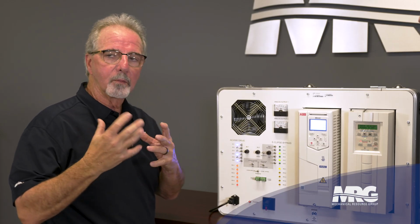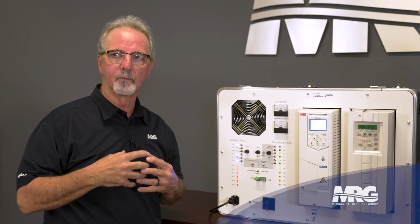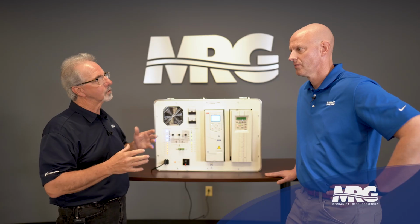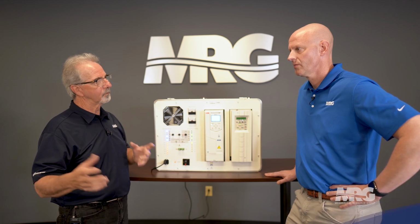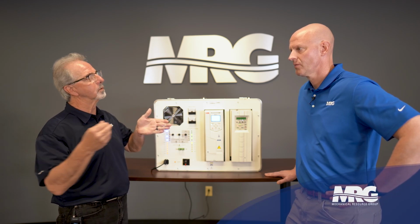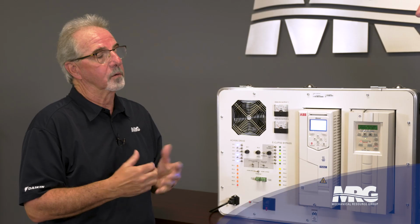Now remember, guys, we don't want smoke to invade the stairwells because that's your evacuation point. Those doors are going to be opening and closing quite a bit. If there's smoke on the floor and you open the door and there's not more pressure in the stairwell, smoke will come in, and then it's just like being on the floor. Yeah, it turns into a chimney. Yeah, it turns into a big chimney.